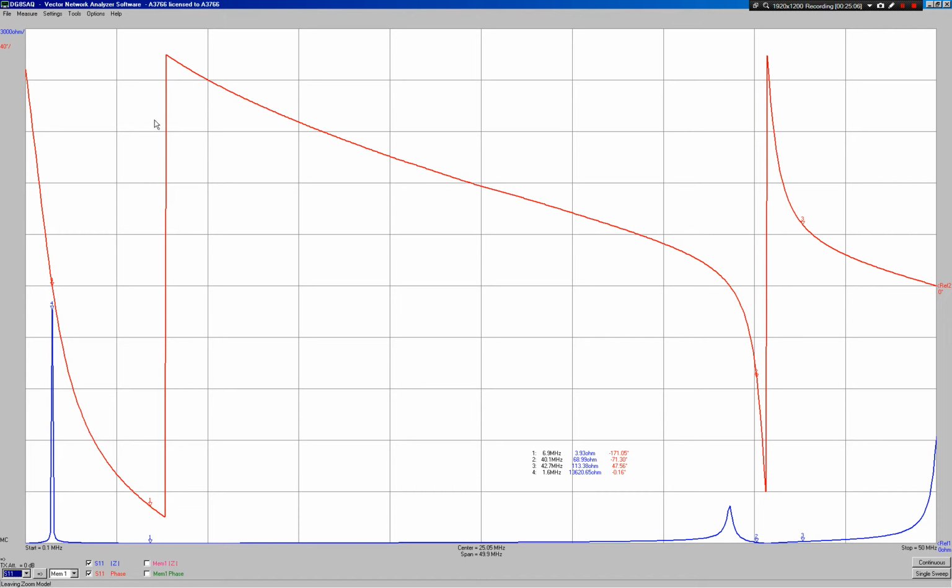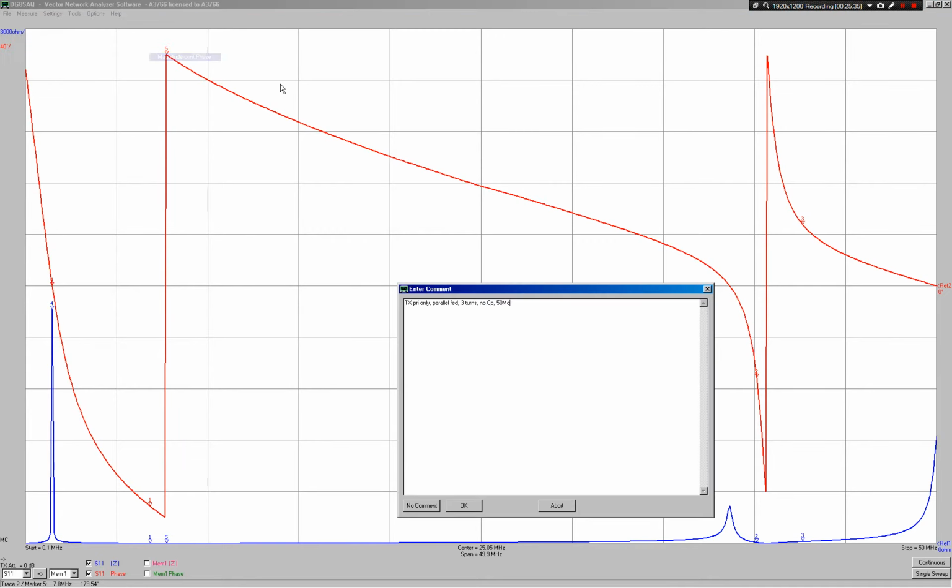You see the phase change here now. Let's add another marker. I want to leave the original markers. Let's add another one here, and that phase change now is sitting at 57.8. So still fairly high, well above the fundamental region for the secondary. So what I'm going to do is wind this out again now. Actually, I will first of all save. I will take a save of this, export the data, next continuous phase, and we only